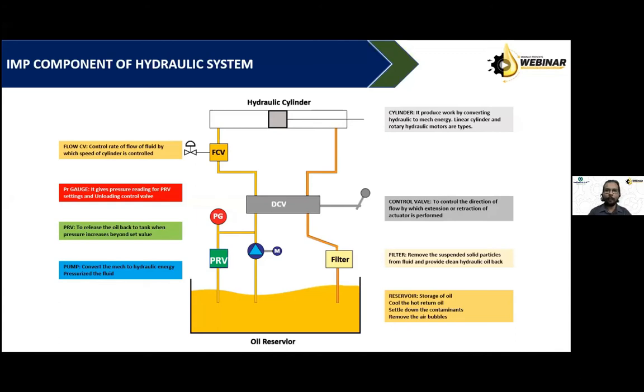Any media or oil entering into the pump should be very clean, because a hydraulic pump has to generate huge pressure with its very tiny either rotary gears or piston cylinders, and there are very fine clearances in the pump.